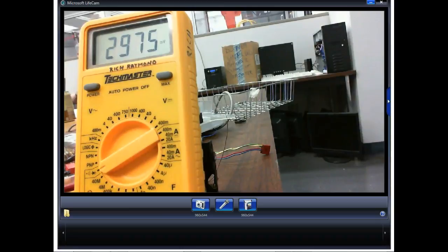So yeah, you can play around with your meter, flip it on, and try to check one of them, which is pretty neat. But what is digital? Digital is off and on and off and on, right? You understand that? And these guys turn off and on and off and on. To make them conduct, we got to have at least 7/10 of a volt on a silicon. We got to have it forward biased by at least 7/10 of a volt. And when I say at least 7/10 of a volt, it don't drop any more voltage than that. So you got to be real careful.